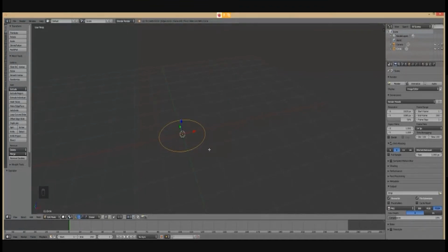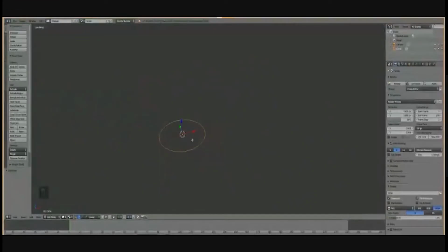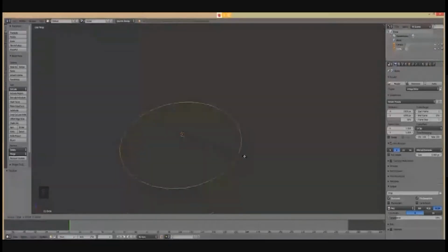All right. So you can combine multiple shortcuts. I'll explain the two shortcuts separately, right? If I just press E, it extrudes. And if I just press S, it scales, whether less or more. However, if I combine the two, I can achieve both.